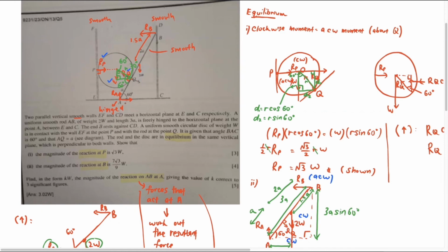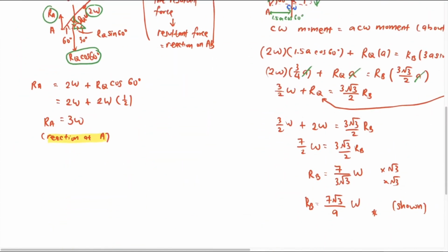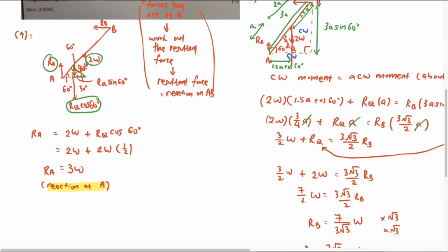Okay, let's take a look. We should have forces that act over here as it is in equilibrium. Let's come back to this picture again. This time I'm going to use horizontal. This is horizontal, acting to the right. Because this part is hinged, I expect forces here, either acting to the right or left. We are not sure, but we simply put one direction first. If our setting is not correct, later you will get a negative answer, then you should know it should be the other way. So I assume it acts this way first, and I call this the hinge reaction.